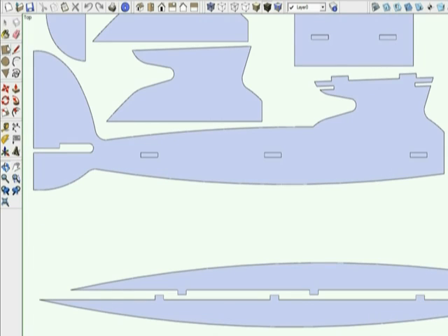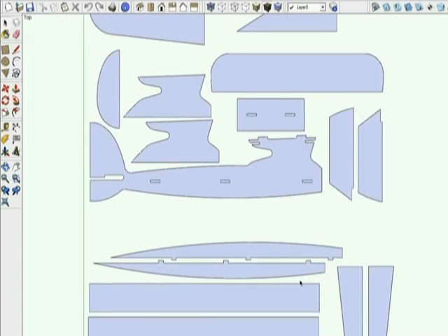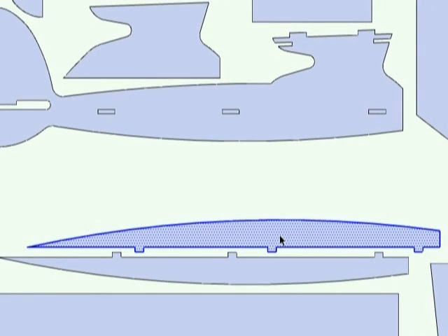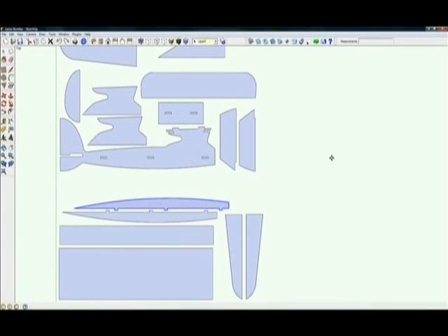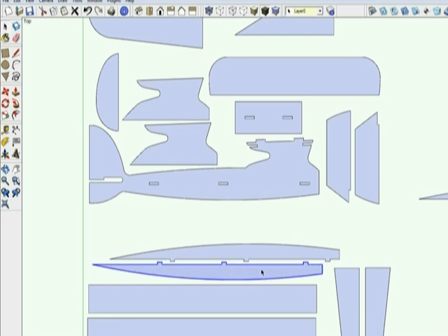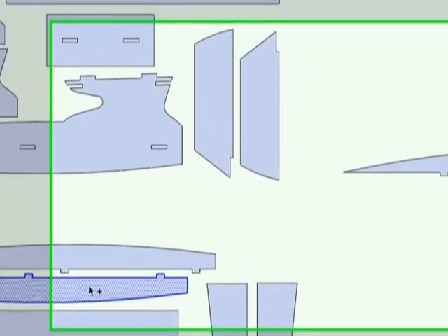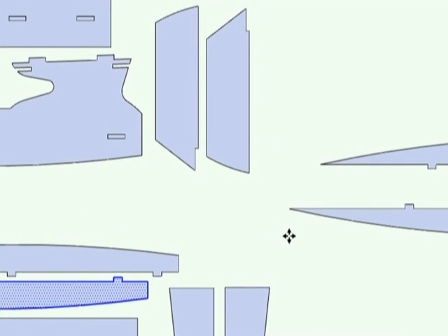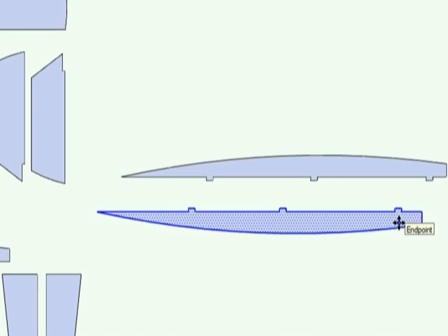If you look at this main piece of the fuselage, you can see how I've got 3 slots, and I've got these side braces that also have tabs. I want to show you just briefly how this all goes together. Now these are 2-dimensional elements, so I can just double click to get them all. And I'm going to Control C and Control V to pull that piece out. Do the same thing with this one. This is a tab and slot method that I like to use.